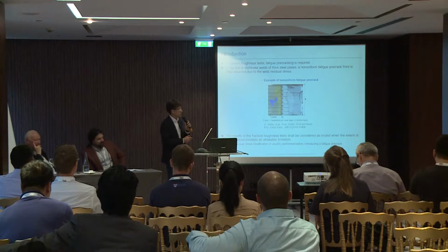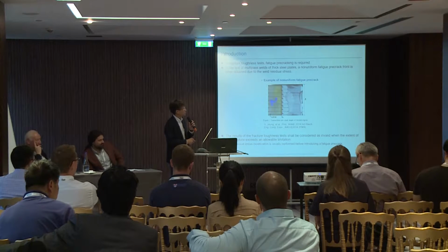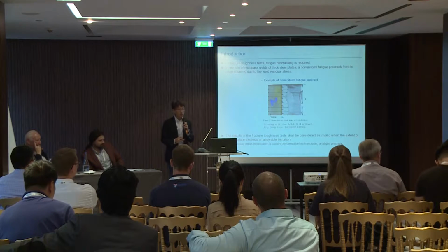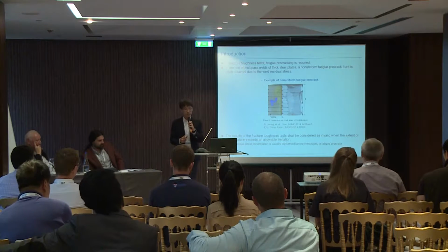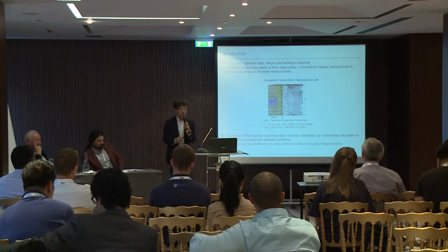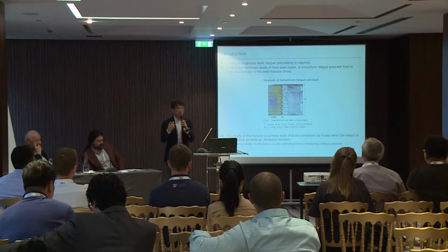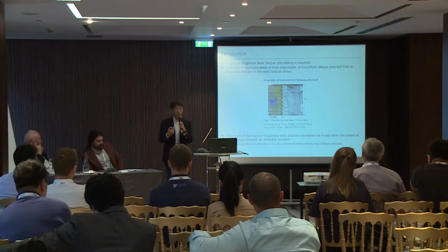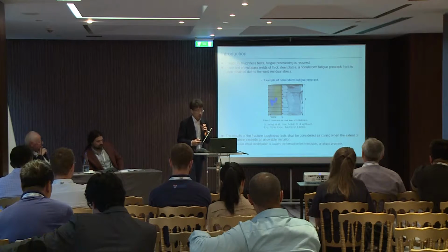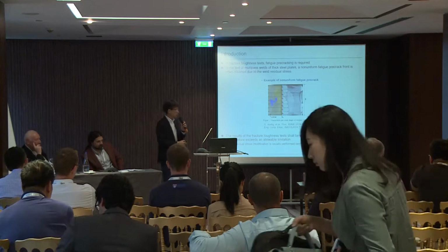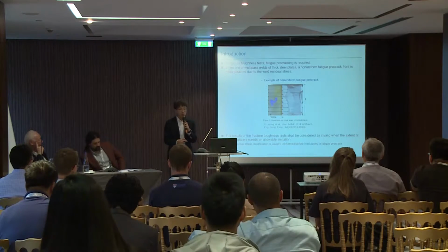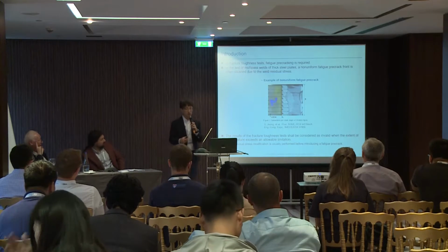So if the pre-crack front is curved like this, the result of the fracture toughness test shall be considered as invalid when the extent of the curvature exceeds allowable limitation specified in the testing standards. So residual stress modification is usually performed before introducing the fatigue pre-crack.